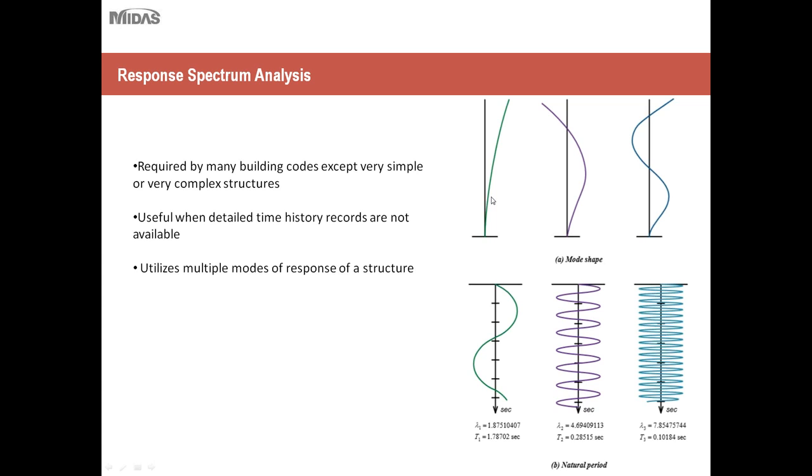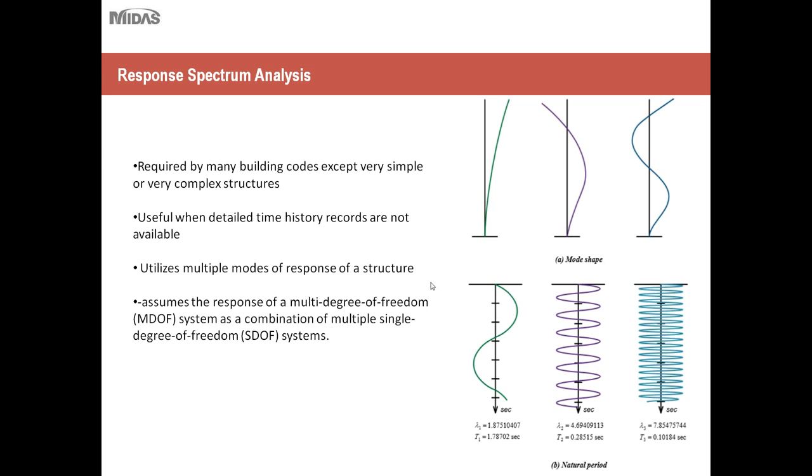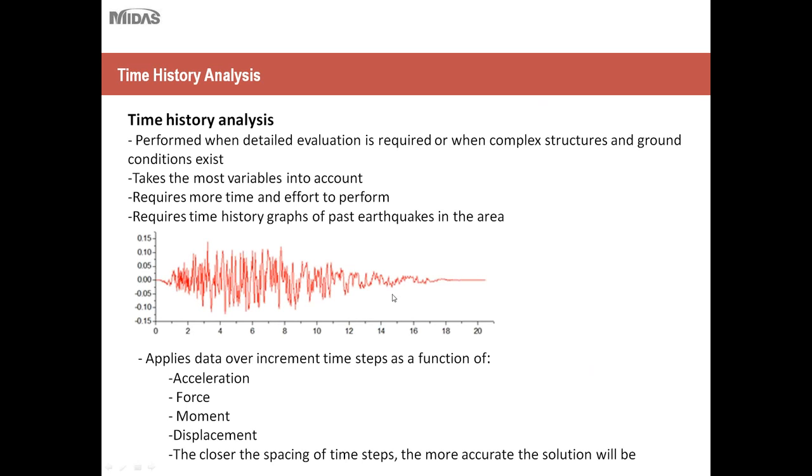That's just something you should be familiar with if you're familiar with response spectrum analysis. It's very important to understand when you're creating a numerical model as well. As I explained, it assumes a responsive multi-degree of freedom system as a combination of multiple single degree of freedom systems. Okay, so now let's move on to time history analysis.